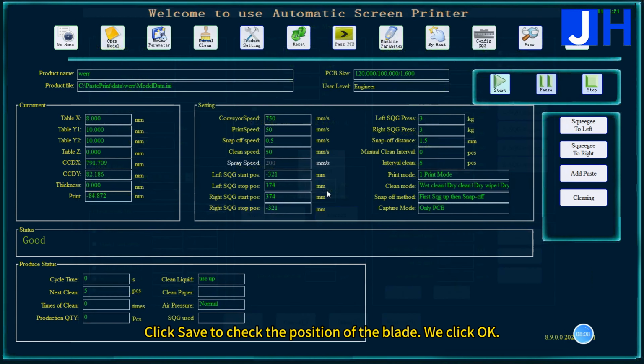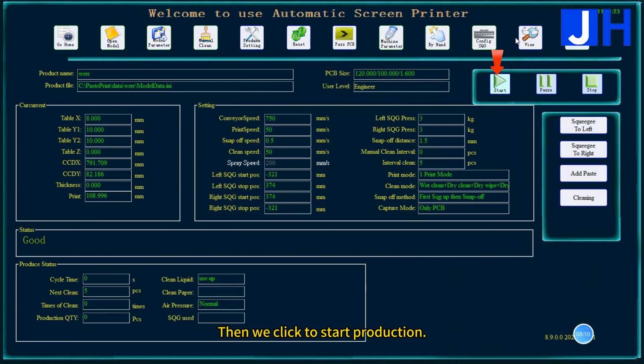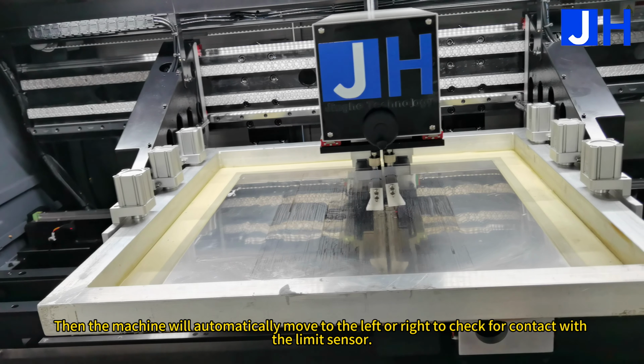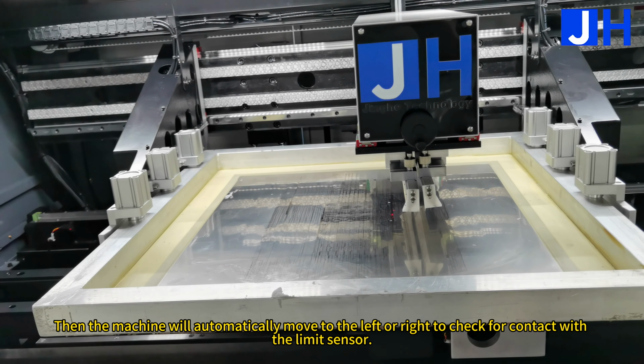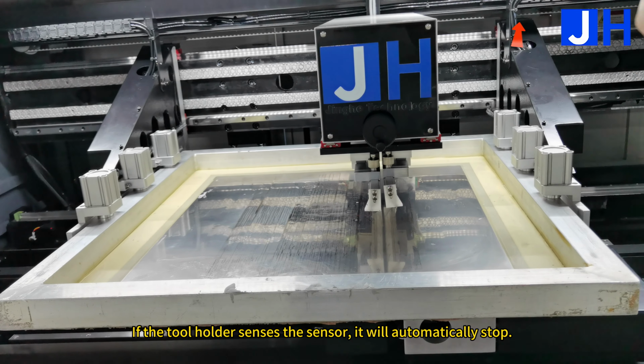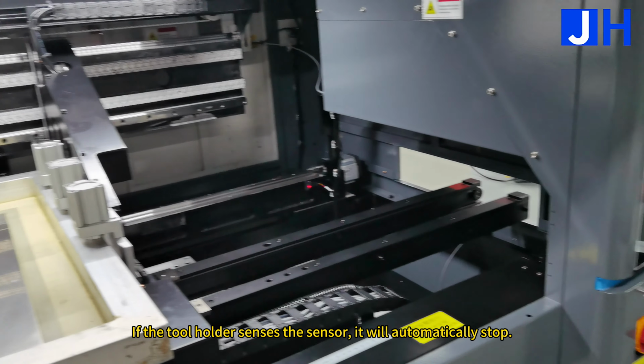We click OK. Then we click to start production. Then a prompt will pop up to check the left and right positions of the blades. Click OK. Then the machine will automatically move to the left or right to check for contact with the limit sensor. If the tool holder senses the sensor, it will automatically stop.